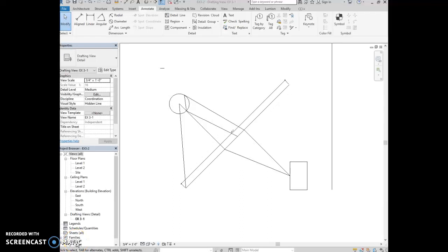In this exercise, we are going to look at edit tools. The edit tools are often used in Revit when you're tweaking designs or making code and client revisions. For example, you will use the design tools, walls, doors, and windows to initially draw the project. Then we use the edit tools to move a wall so a room can become larger, mirror a cabinet so it faces in a different direction, or rotate the furniture per the owner's requests.